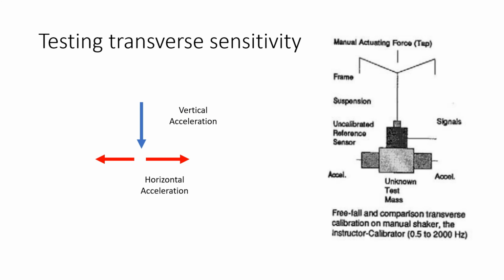In our last experiment, we would like to look at the transverse sensitivity in accelerometers. When you vibrate an accelerometer in the axis it was not supposed to operate, we can still get measurements. This is due to the transverse sensitivity of the accelerometers. When you buy an accelerometer, the manufacturer usually tells you what the transverse sensitivity is. To find out what the sensitivity is experimentally, we have to have another gravimetric apparatus where we bring the accelerometers into free fall and we look at their out-of-axis measurements.